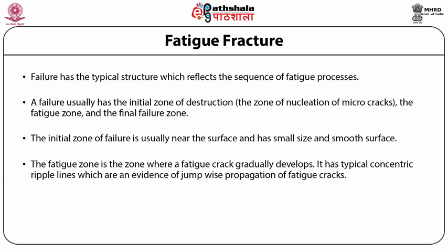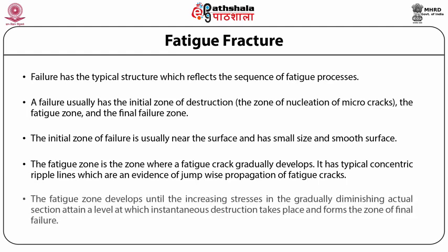It has typical concentric ripple lines which are an evidence of jump-wise propagation of fatigue cracks. The fatigue zone develops until the increasing stresses in the gradually diminishing actual section attain a level at which instantaneous destruction takes place and forms the zone of final failure.